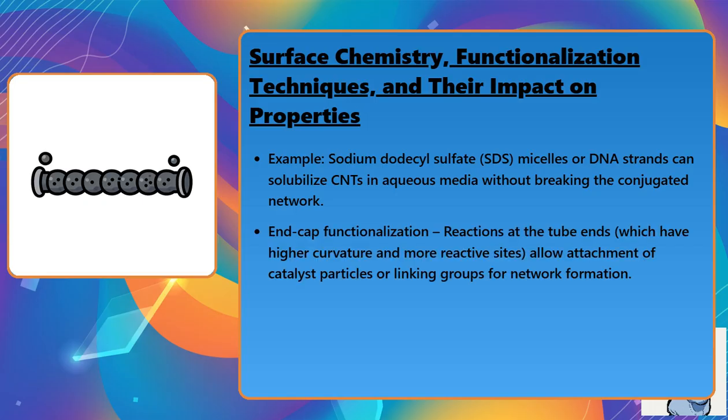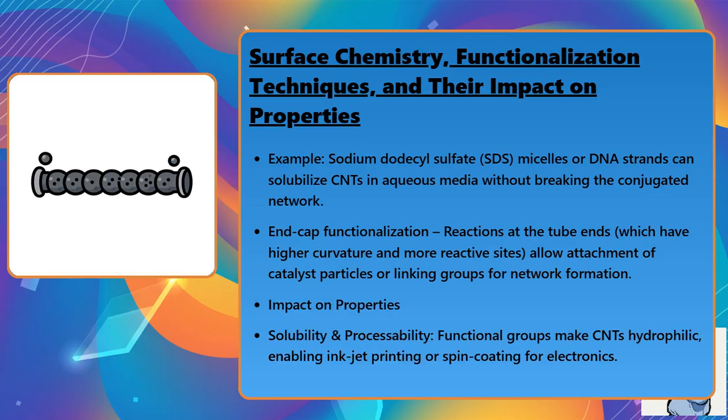End cap functionalization reactions at the tube ends, which have higher curvature and more reactive sites, allow attachment of catalyst particles or linking groups for network formation. Impact on properties. Solubility and processability. Functional groups make CNTs hydrophilic, enabling inkjet printing or spin coating for electronics.